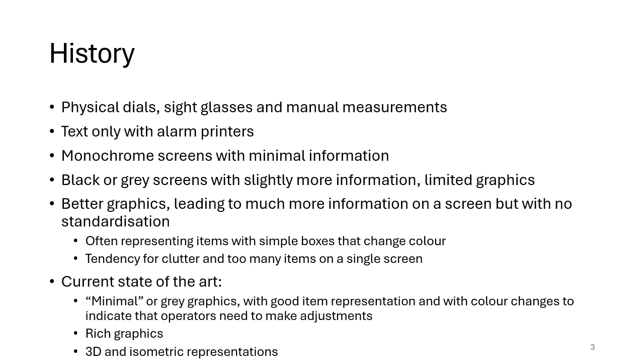So the current state of the art is more about minimal graphics. Often we start with a simple grey screen, and the idea there is we have very good item representation, so almost photorealistic images, or at least the outline of the device, and that makes it easy for the operator to understand what it is they're looking at. And then we have minimal color changes to indicate that operators need to make adjustments.